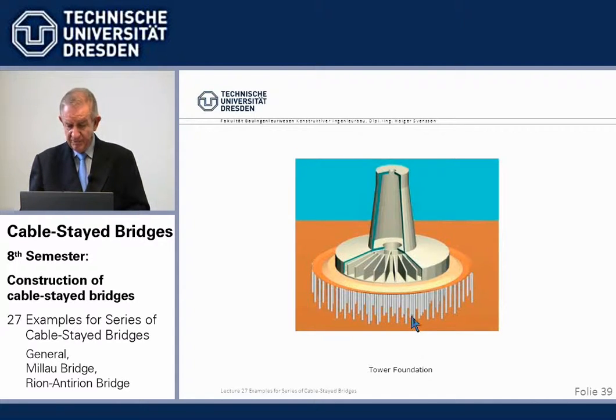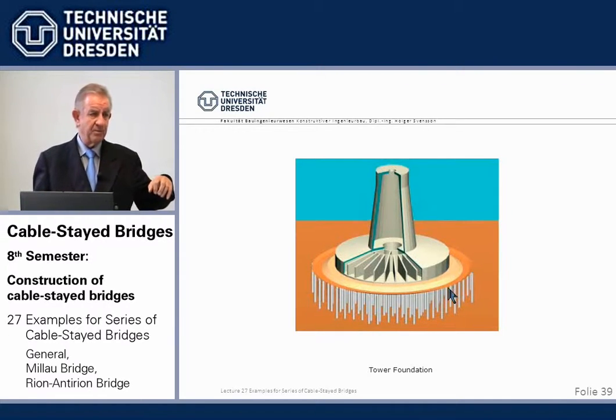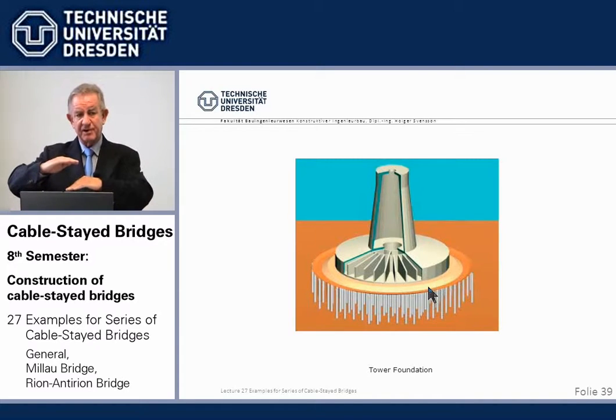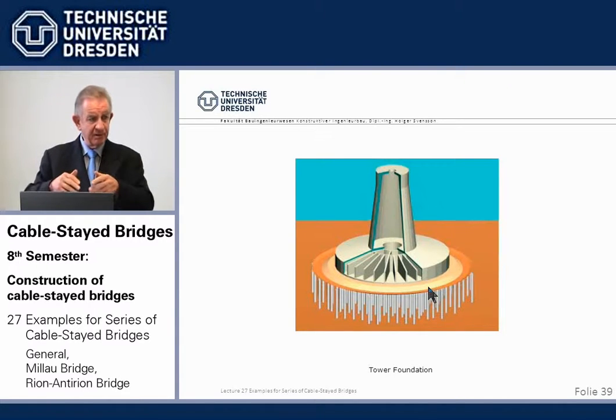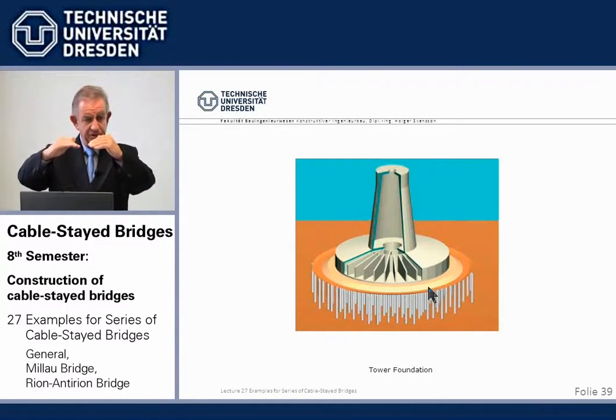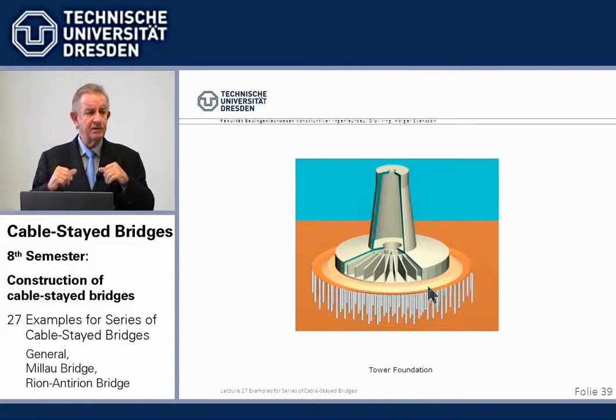And from the bottom up, after dredging the top layer of clay and mud and dirt away, there is, I think, a 2 meters thick differentiated layer of gravel, starting with rounded river gravel, going to broken gravel. So there is a stepping of the inner friction.